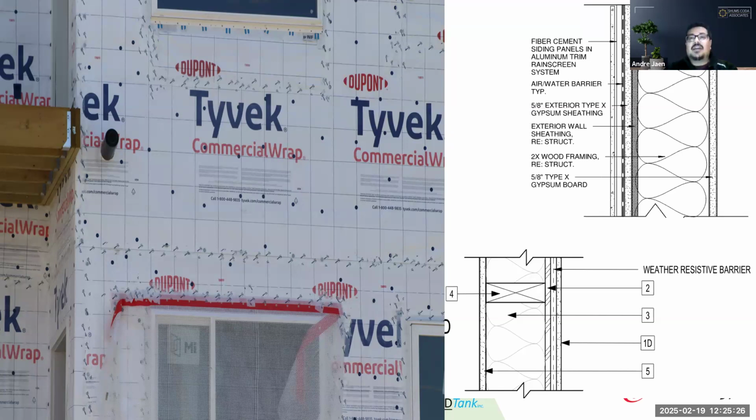Is the selected product on the outside there? First of all, I don't know what it is if this is the only plan that I've gotten, right? It just says air and water resistive barrier. Do I know of products that can do that? Yes, Tyvek is definitely one of them. If I'm out there as the inspector on this, that means that I have separate installation requirements. And if you go and visit their manual, you will see that for penetrations, they'll have additional taping requirements. For windows, anything that penetrates that membrane, they'll have separate installation manual requirements for it.